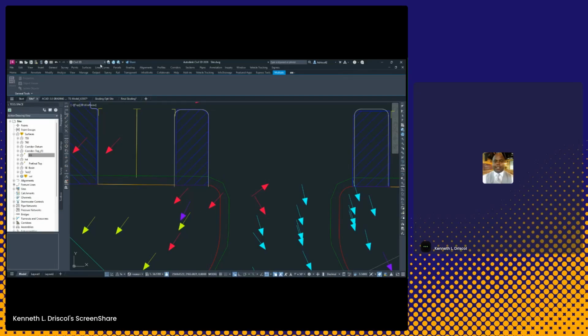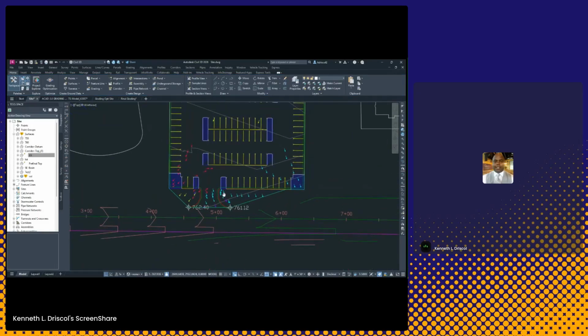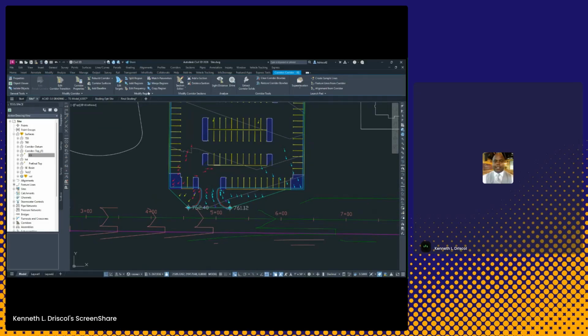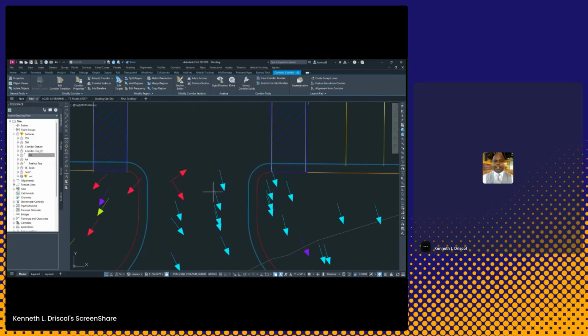Everybody get that? And from that, it looks kind of jaggedy, but clearly we can clean that up pretty quickly by saying edit frequency. And frequency in here, this whole region. So we'll say tangents, we'll do 10. Curve increment, we'll do 0.2. And select OK. Now it's nice and smooth.